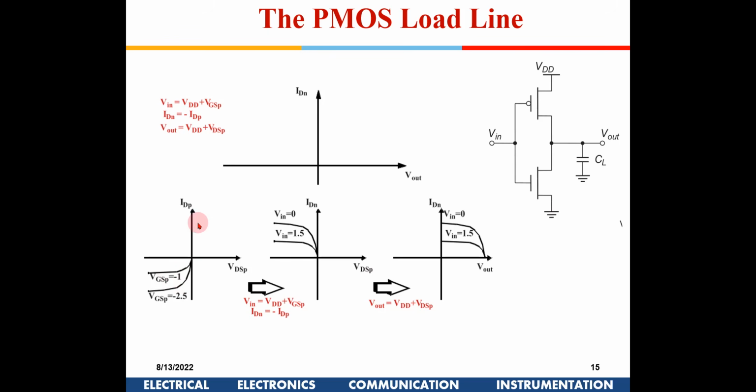IDP versus VDD. This is just the PMOS characteristics. Gate source characteristics. This is negative. As you keep increasing negative, PMOS current increases, right? Because this is gate source. Source gate has to increase, right? So gate source means it will be in the negative direction. Is it okay? And I source will increase. I drain is negative, right? For a PMOS, the top one is source, bottom one is the drain. So in this case, I am plotting I drain, and hence it is on the negative side.